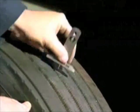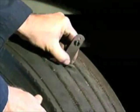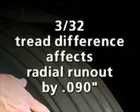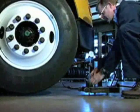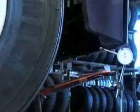If a 3/32 or greater tread depth difference is found, then the tire is worn out of round, and the cause of this wear will have to be determined. A 3/32 tread depth difference will affect your radial runout reading by 90 thousandths of an inch. On a new tire mounting, or if the tread depth difference is less than 3/32 circumferentially, position the tip of